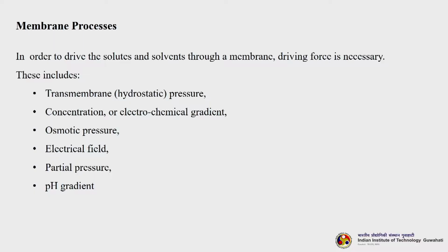Since we cannot measure chemical potential directly, we have to express the driving force in a measurable quantity or parameter, which can be transmembrane or hydrostatic pressure, concentration or electrochemical gradient, osmotic pressure gradient, gradient of electric field, partial pressure, or pH also. So, as you can see, all these parameters are different gradients and are readily measurable.